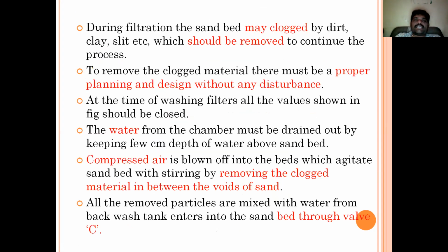And the precautionary step is here: the sand bed may be clogged by dirt, clay, silt, etc., which should be removed to continue the process. Understand? To remove the clogged material, there must be proper planning and design without any disturbance to the working process of the unit. At the time of washing filters, all the valves shown in the figure should be closed.